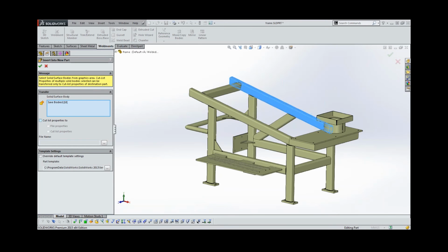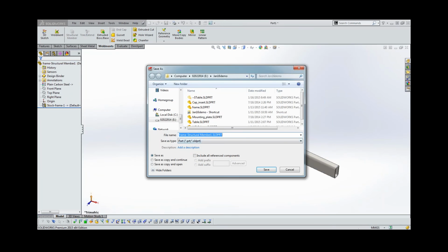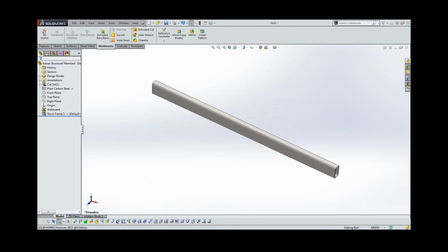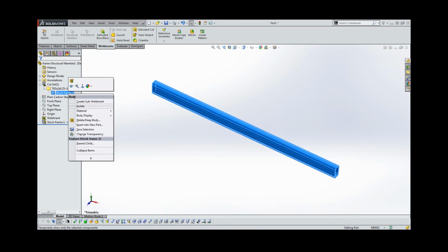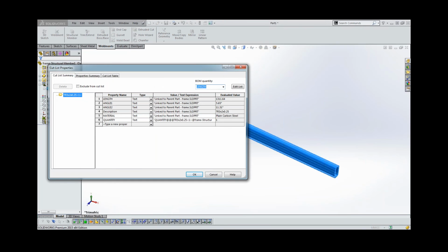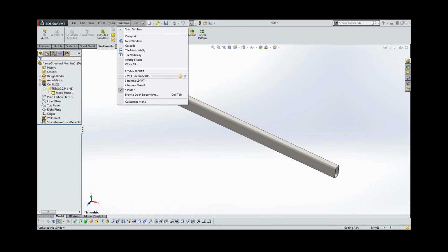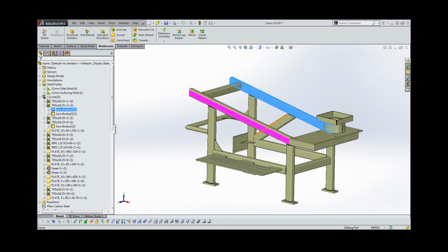Cut list. Cancel. And then it brings all those over with us for you now. So you have all your same cut list items still there. They're linked to the parent, and so you've got to keep that parent active while you do it. So that way, anything you do with the parent part is going to go ahead and populate down into that new saved body.